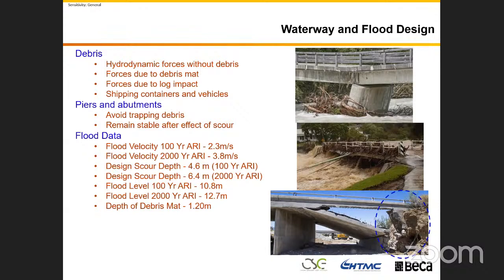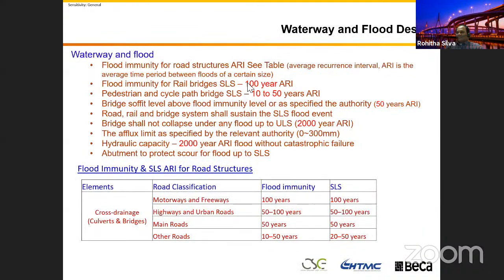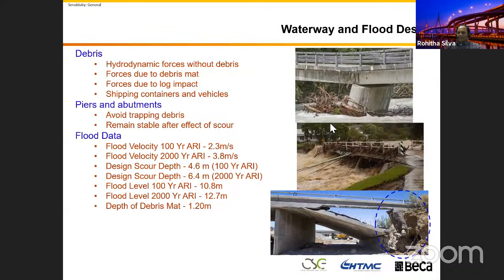So your position is, if we laterally restrain the bridge, which I think is the case in Windsor Bridge, that's okay, isn't it? We don't have to design anything for 100 years all the time. No, I think we had to design the bridge for 1 in 100 year for the SLS and 1 in 2000 year return period for the ULS. We had to design for these dynamic forces and the scour, everything.